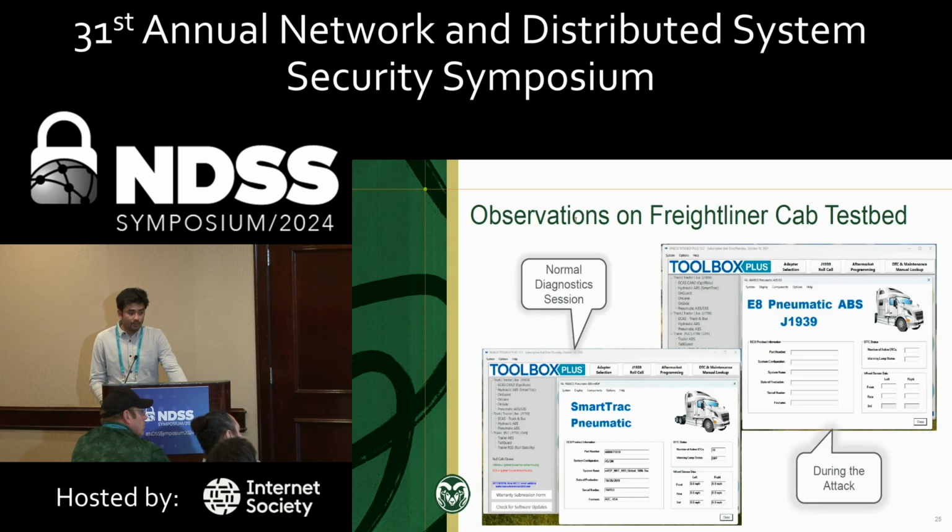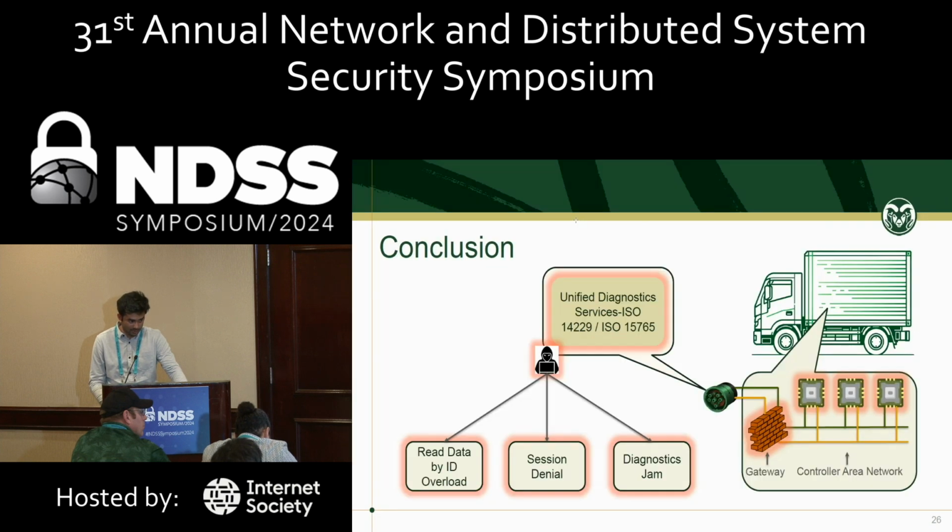The same was observed on the Freightliner test bench. As you can see from the screenshot, during a normal diagnostic session, it managed to get all the data using a normal UDS session. But during the attack, the data was just not present. It could never gather the data because the ECU was confused in these state transitions between waits and CTSs.